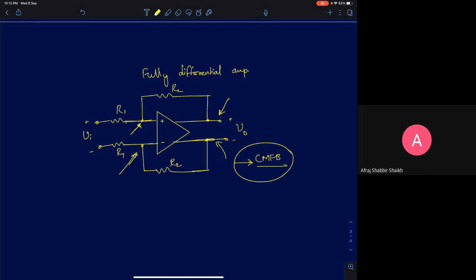So the way in which we will look at this course is that we will see in what application the op amp is used. First, I will discuss the different architectures, how to realize large gain, what are the different circuit realizations of an op amp that one can build to realize a very large gain. So the fundamental goal is to build a large gain. So that's what an op amp is. An op amp is a high gain amplifier. What are the different ways of building it? And what is the best architecture of an op amp that an engineer can pick for a specific application?